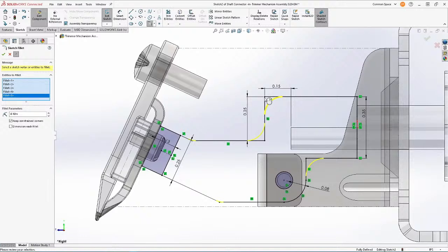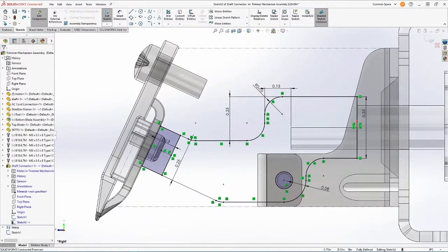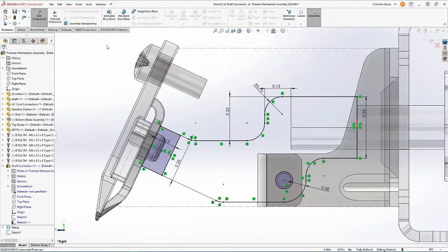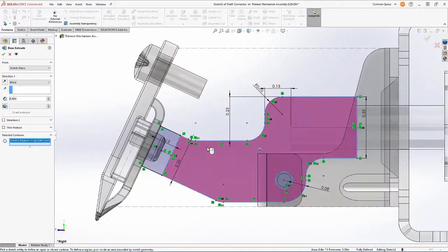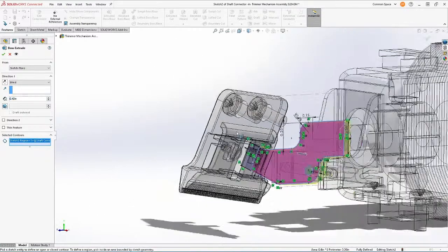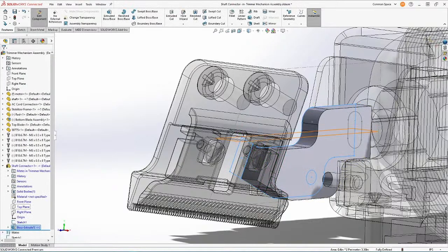Now for the fun, all the fun is in bringing it from 2D to 3D. So I'm going to use an extrude feature. Now, I'm not going to choose a mid-plane extrude or anything fancy because I'm simply going to model half of this component instead, because I'm going to add some detail to this half so then I could just basically mirror the other half without having to duplicate any of my efforts. And this is just a great tip for design intent in general. So you don't waste time modeling the whole thing, you just model half, mirror the other half.